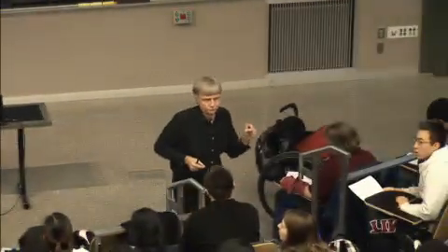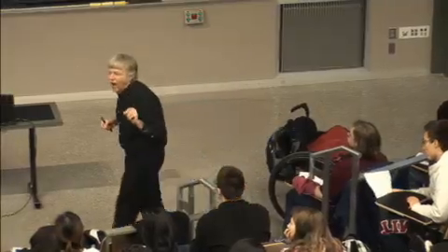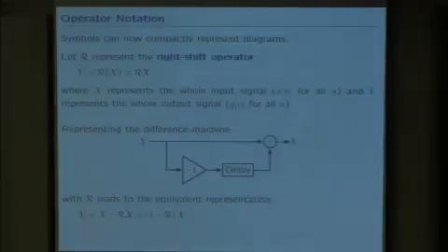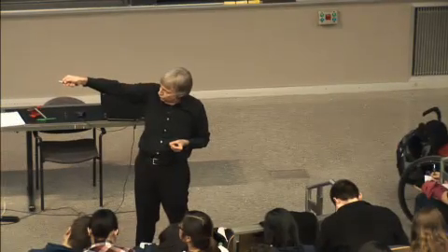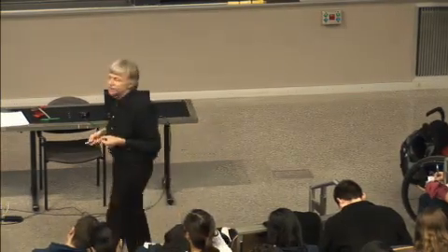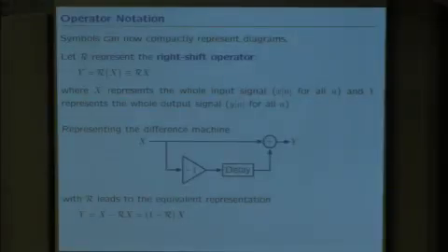An operator is not something that works on a number. Operations work on numbers. Operators operate on signals. So I'm thinking about operator expressions. I'm going to try to formulate the transformation from the input to the output in terms of operators. The way I take x, which is the input, and turn it into y, is to operate on it with the operator 1 minus R.